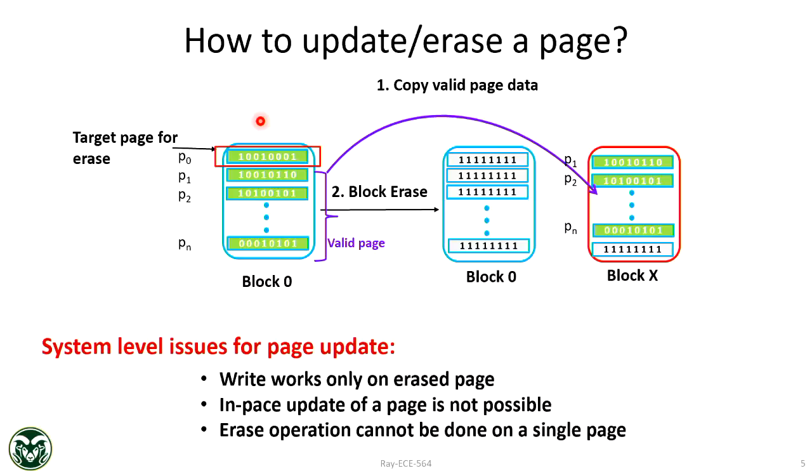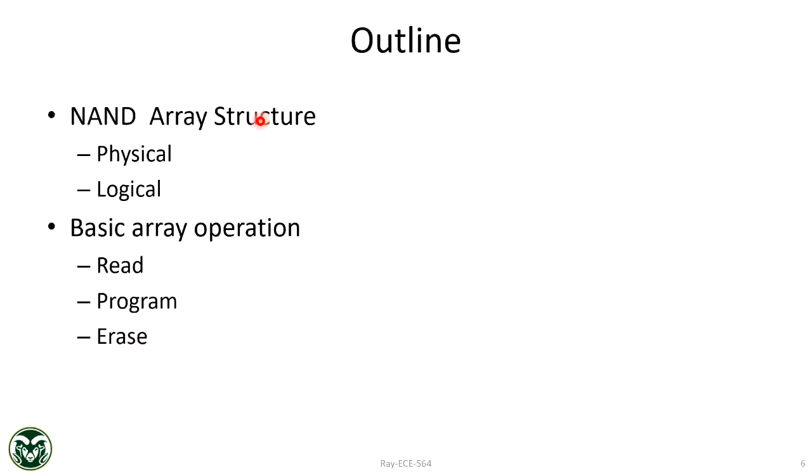Separate companies make them. For example, Marvell Semiconductor just makes NAND controllers. SanDisk, for example, makes just NAND chips, or Micron makes NAND chips. If you open up your SSD, you will see there is a square-shaped big chip. That's where the NAND controller goes in. So that's just to tell you. Maybe later in the course, if we have time, I can give you an overview of the NAND controller and some system functions. But today's class, we'll stick to basics. Basics here is read, write, erase, and how those operations are performed at an array level.